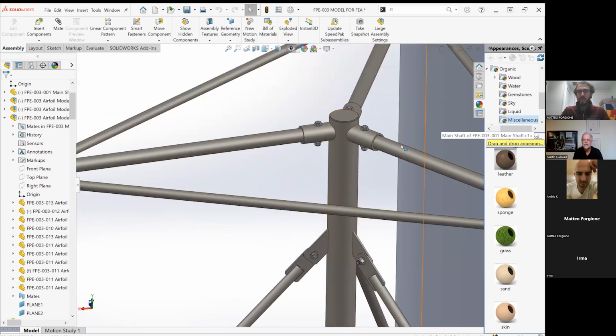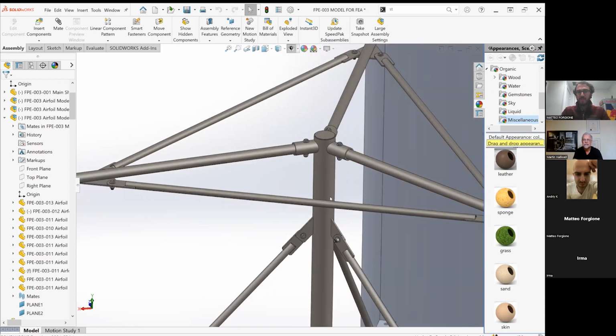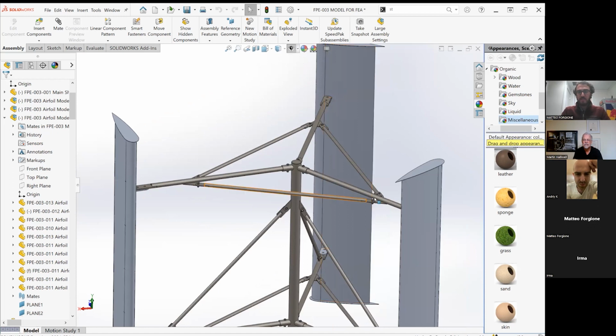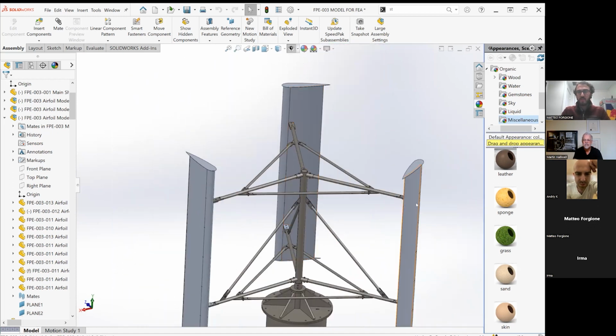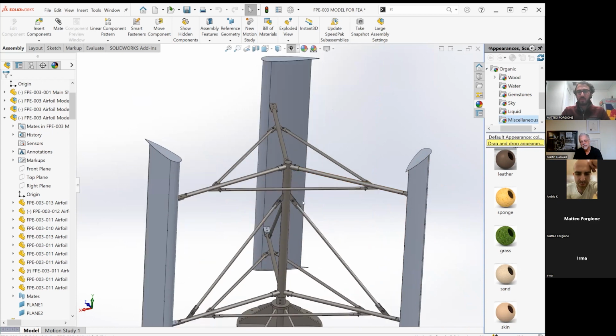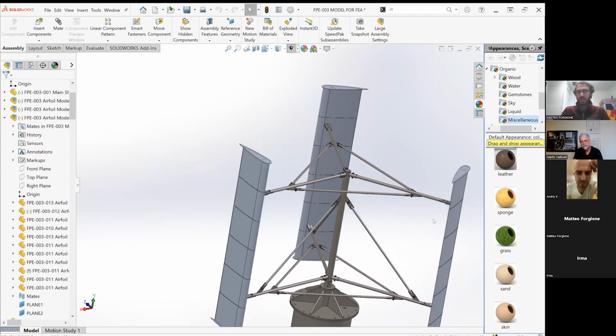So you have basically a positive connection socketed in here onto your main shaft, and then everything else is bracing to brace it for the rotational torque, and then some vertical as well, because we can't really rely, I mean, you could potentially rely on this for any vertical moment, but really wouldn't want to. So we have this vertical braced as well.